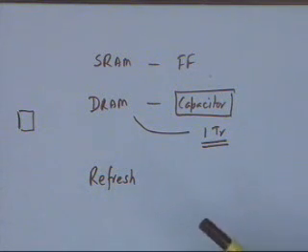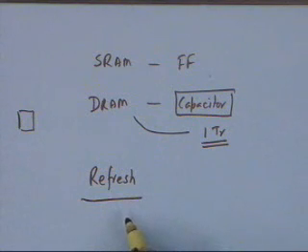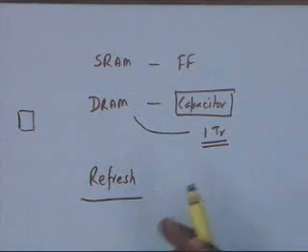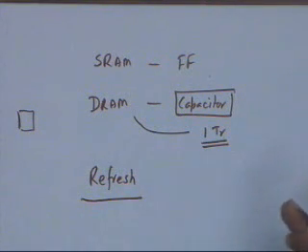Of course, how much refresh it requires depends upon your design, like how often you need to refresh. But interestingly, a lot of DRAM circuitry today is made in such a manner that if you access even one location in a block, the whole block will be automatically refreshed. The circuitry is built within the DRAM itself.